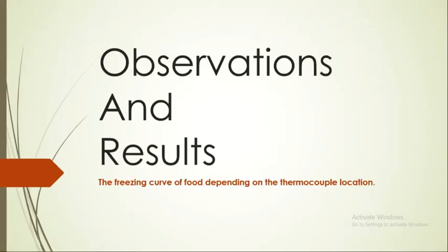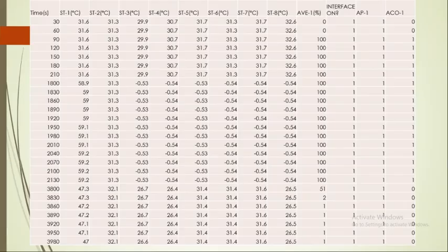We have placed 3 different products and run our unit, and you can see the time I have taken for a certain part of our running time. As you can see, this is a very long run in order to gain these temperatures. ST1 is the temperature of the discharge line of the compressor, although ST2 is on the suction line.